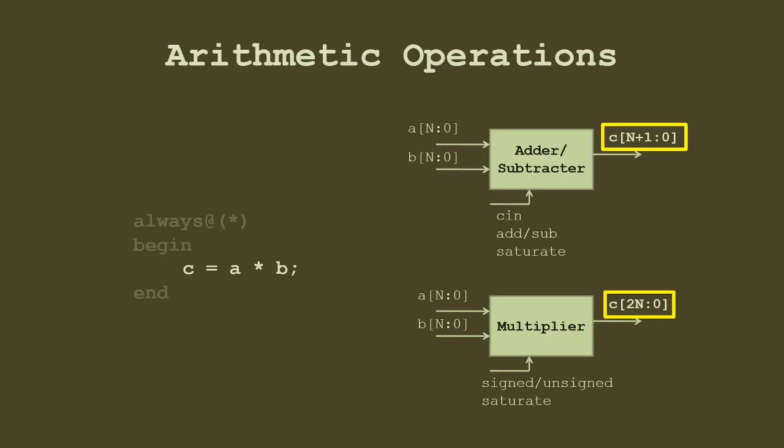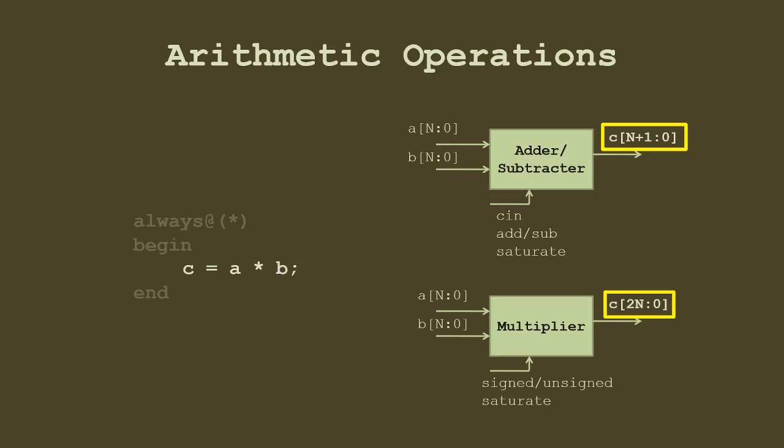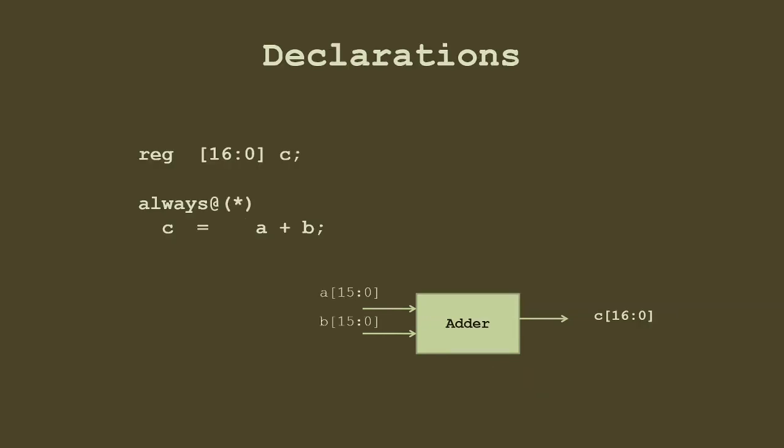Okay, so one thing that I haven't covered is how we declare these variables. These variables can be declared as reg or var. This reg is kind of an idiosyncrasy in Verilog. If I had been making Verilog, I would have used only one type, maybe wire. There was no need for reg. So don't confuse reg with register. It has nothing to do with register.